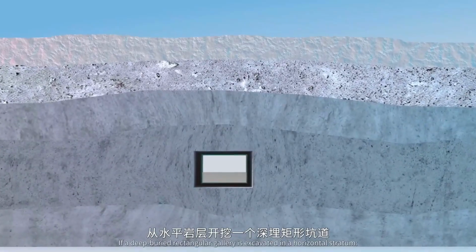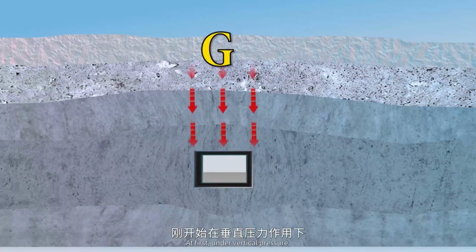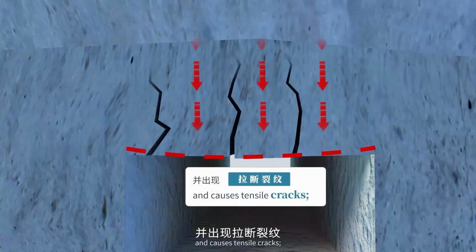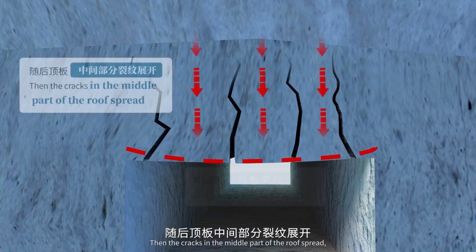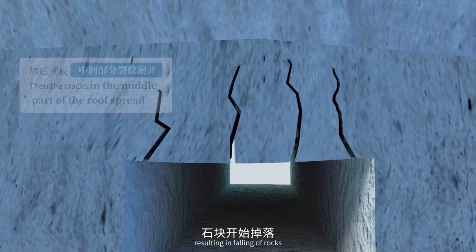If a deep buried rectangular gallery is excavated in a horizontal stratum, at first, under vertical pressure, the surrounding rock on the roof of the gallery begins to sink and causes tensile cracks. Then the cracks in the middle part of the roof spread, resulting in falling of rocks and sharp increase of vertical pressure.